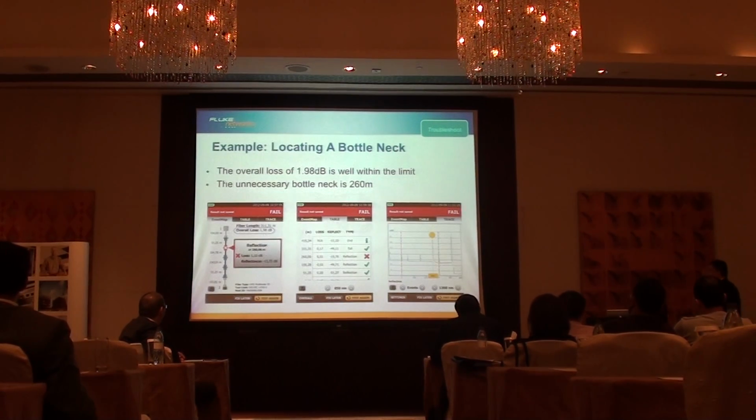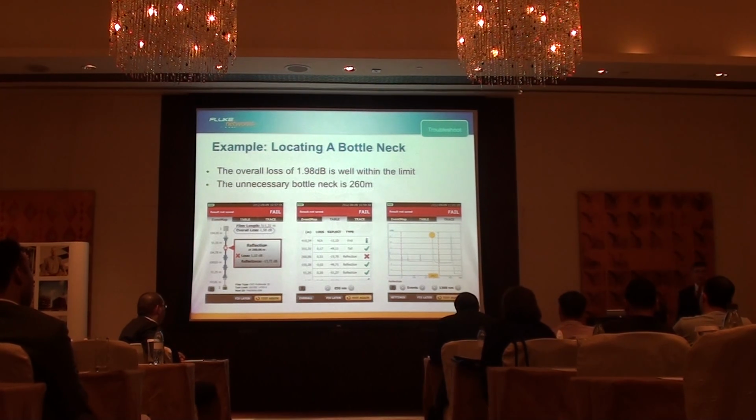So that's quite common. And then the nice thing about the OTDR that we provide is that it will give you the full channel. It will tell you whether you have a ghost or you have a splice or you have a coupling, how much loss it is against the standard, whether you have a pass or a fail. And so you can get individual-based pass-fail results, as I mentioned, which is not seen in any other OTDR as I know of. So we get pass-fail, and you can even certify the interface as well, and give you pass-fail for that one. So you can see with the OTDR graphic user interface, you can see where the problem areas are,